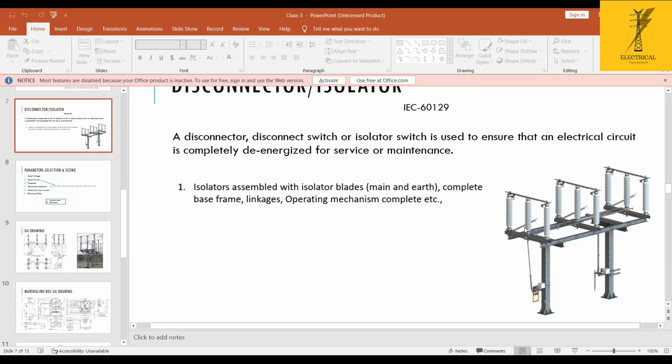It is very good advice to take the insulators directly from the manufacturer, so you will not find difficulties when setting it up, because for these insulators the PCD, pitch circle diameter, where the 3 holes will be, has to be exactly maintained. It will be difficult for us if you purchase outside.